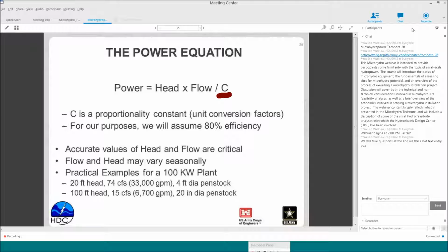As this expression is the ideal power available in the fluid flow, then to get an actual approximation of the power output you could actually achieve with any hydro unit, we would need to apply an efficiency rate to this ideal. For microhydro range units, we might assume 80%. And for, say, the cross flow unit that I introduced a moment ago, that 80% is a reasonable number.